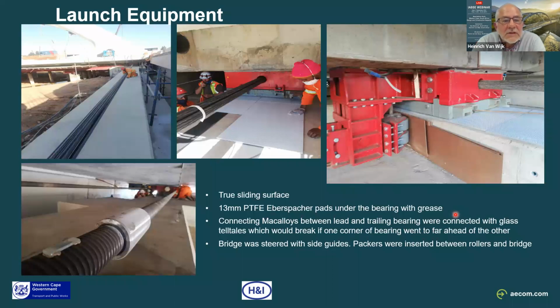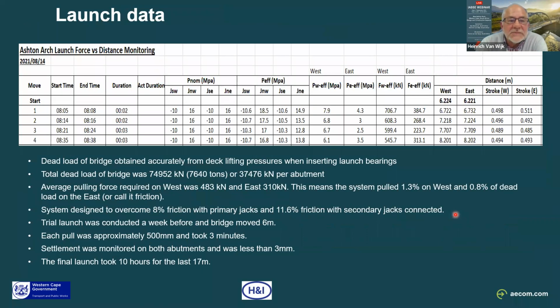That's just some closer pictures of the launch bearings, the launch pads being swapped as the bridge gets steered into position, and you can also see the side guides, which we've fed with packers to actually guide the bridge as it moved across to its new position. Just some statistics. The system was originally designed for up to 11%.